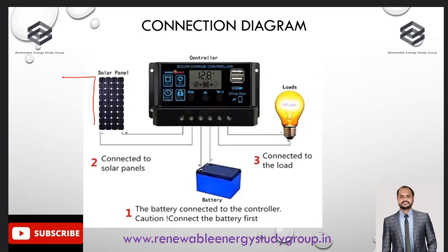We have 3 panels that we have connected in the parallel combination. And this connection we have to give to the controller. The controller's work is to control the amount of voltage and current that we are getting from the panel, try to utilize the maximum amount of current and voltage extracted from the solar panel, and give this current and voltage in the proper format to the battery. When the battery is discharged, it supplies the current and voltage. When the battery is overcharging, it basically cuts off this power. So this is the intelligent functionality of the MPPT charge controller that we get in the market.